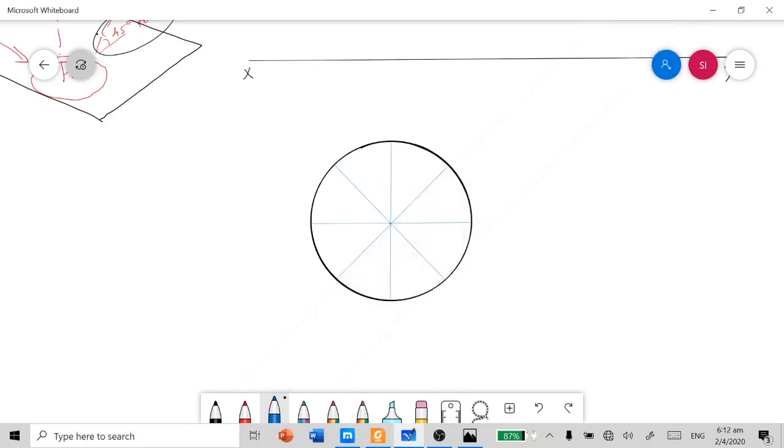After splitting it into 8 equal parts, you can mark the generator points by marking alphabets and numerals in the base and the face respectively. One more time I am telling you that they are not corners. Okay, they are generator points. For convenience only we are making them. The same way for the face.